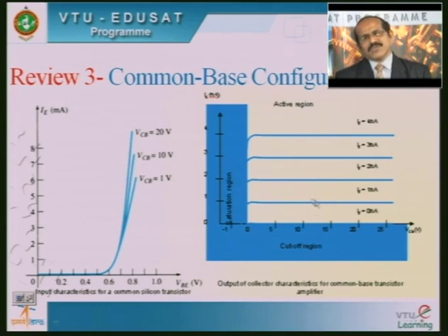Why is the active region preferred? Because we have a flat curve, that is, a linear region. The second point is that there is an equal distance between these curves, and that is very much required for faithful amplification.